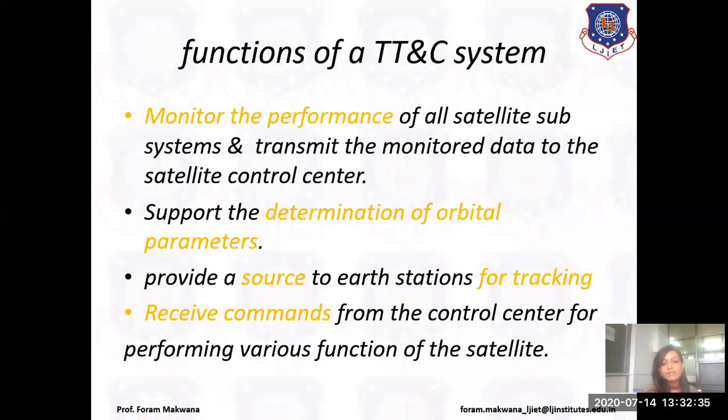All right, as well as we have already studied different orbital parameters. The most important are apogee, perigee, argument of perigee, eccentricity, semi-major axis, as well as true anomaly and mean anomaly, right? So we have to determine what are different orbital parameters, as well as it also performs monitoring of the different performance of satellite subsystem.